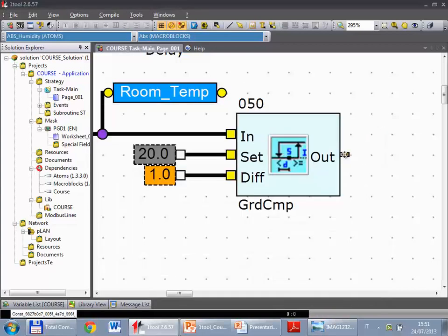I will show you this. Right click the pin, and you have to click exactly on the pin when the cursor becomes an aim, a pointer. Right click, connect to a variable or connect to a constant. In this case, we'll use connect to a variable.